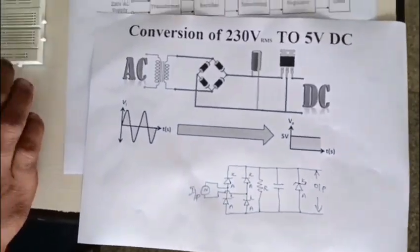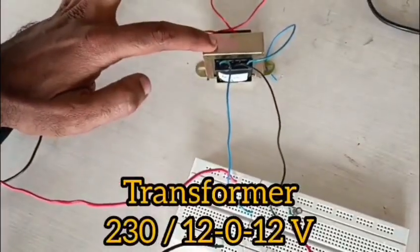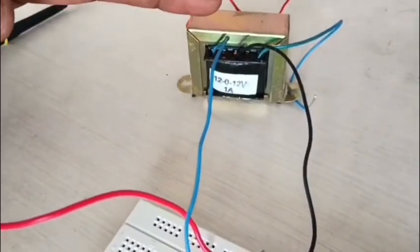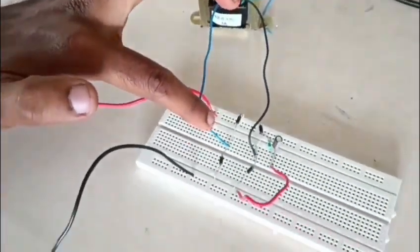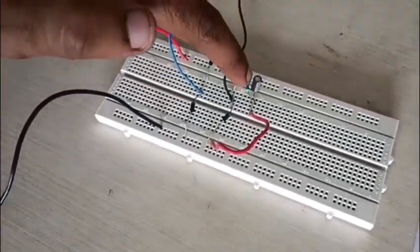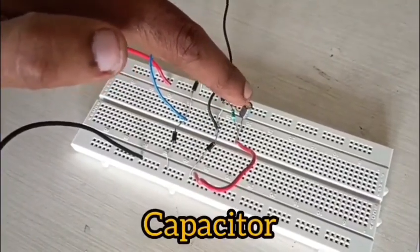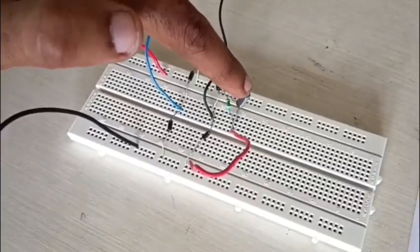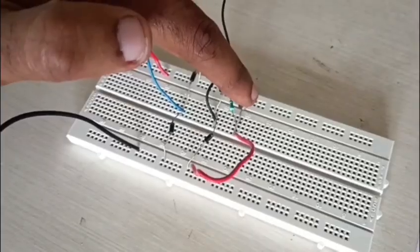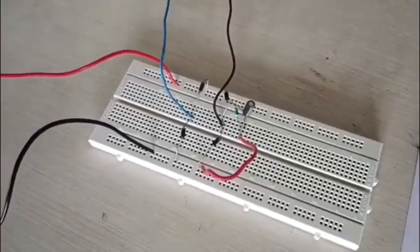Now we will see the practical circuit. Here we are having a transformer. This is a 230/12-0-12 volt transformer, and the output of the transformer is fed to a bridge rectifier. The bridge rectifier output is fed to a resistor. Then with the help of the capacitor we are going to smoothen the output waveform. Then after seeing this waveform, we will connect a 7805 IC to get a 5 volt DC supply. Now we will check the output waveform.